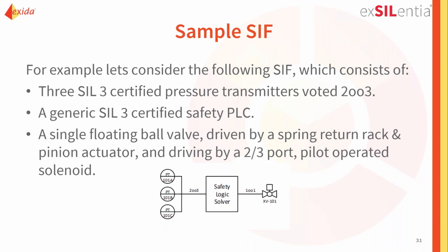But it would be wrong to just start calculating PFD average values for a final element and then concluding certain SIL levels that we achieve, because SIL level is obviously part of the overall safety instrumented function. But then our final element is going to consist of a single floating ball valve, which is driven by a spring return rack and pinion actuator, and that is operated by a 2-3 port pilot operated solenoid. So that's our final element assembly, and that's something we model.